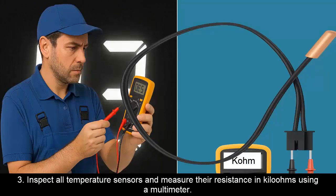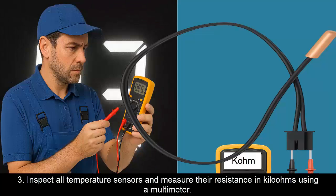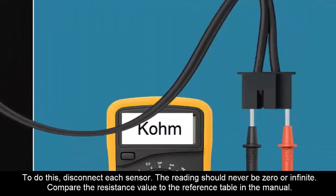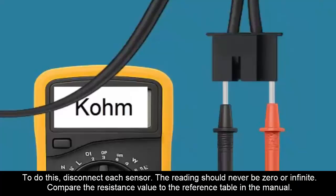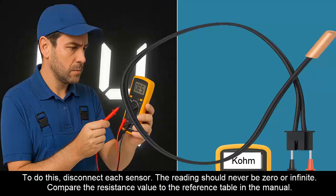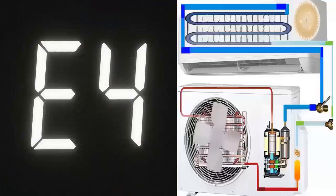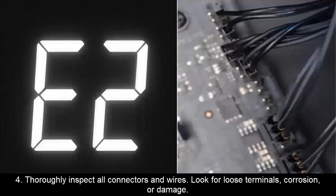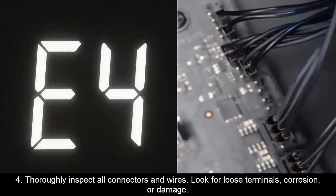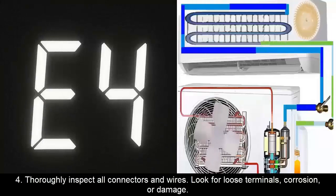3. Inspect all temperature sensors and measure their resistance in kiloohms using a multimeter. To do this, disconnect each sensor. The reading should never be 0 or infinite. Compare the resistance value to the reference table in the manual. 4. Thoroughly inspect all connectors and wires. Look for loose terminals, corrosion, or damage.